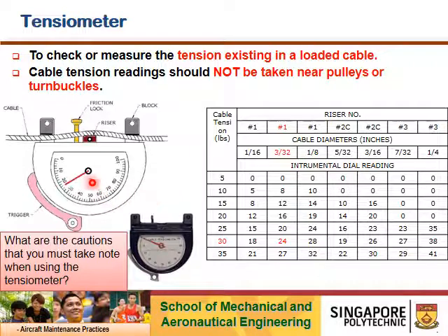Let's say we are following this example, a 3/32 cable, with this riser engaged, and the reading is about 24. The indication on the tensionometer displays 24, right? Then you go down this column and look for 24.